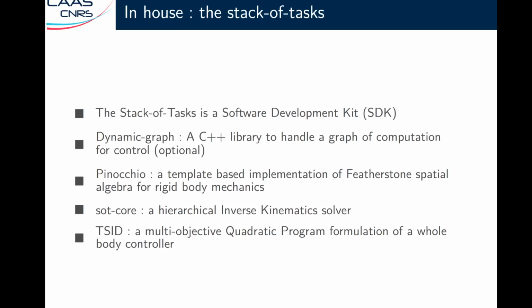What we are providing at LAAS is a software development kit that we call the stack of tasks to implement a whole body controller. It is composed of a dynamic graph, which is a C++ library able to handle a graph of computation for control in a similar manner to Simulink. Of course, this is optional. You can also use Pinocchio, which is a template-based implementation of the Featherstone spatial algebra, which is extremely useful for rigid body mechanics. And Pinocchio is extremely efficient.